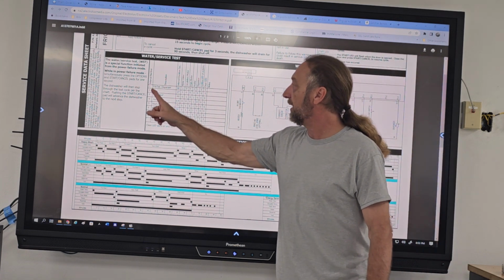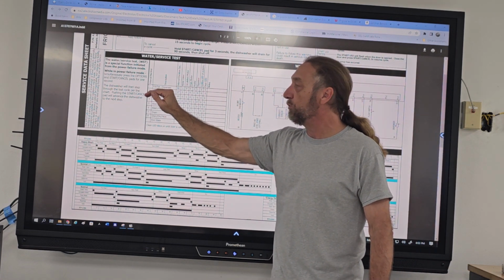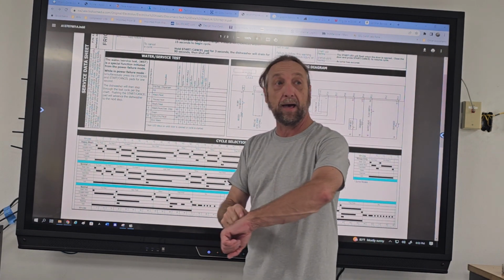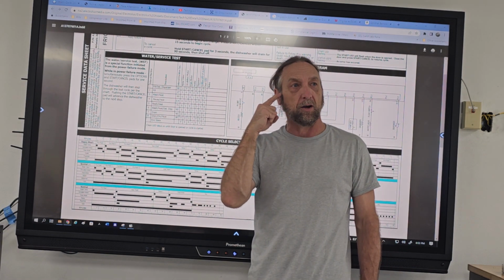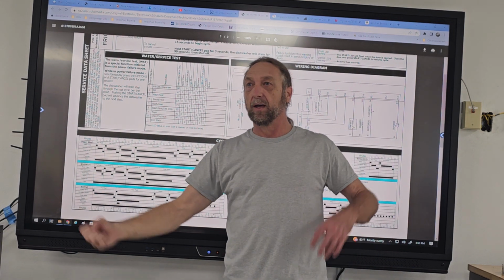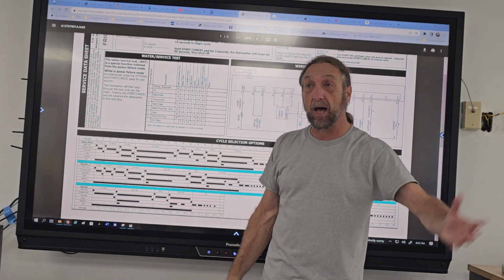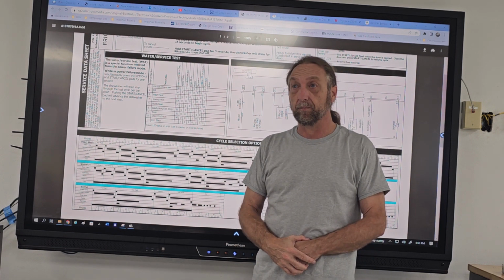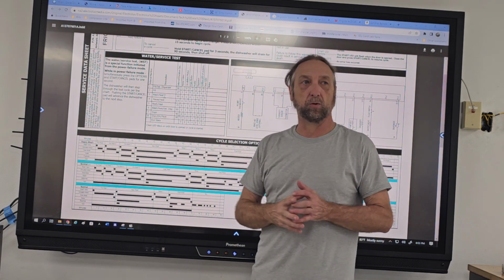But I want to go here, get it into this diagnostic mode and let it go. And it moves by itself step by step. But I look at my watch and say, okay, after 1.5 minutes, it's going to stop filling, it's going to start washing. So I'm going to hear the water valve turn off and the wash motor turn on. At that same time, what else is going to happen? The heat's going to come on. The heat's gonna come on, yeah. And at that point, I can troubleshoot that out.